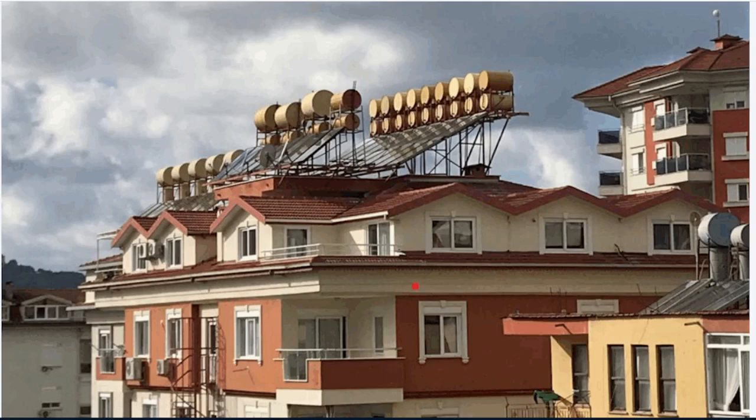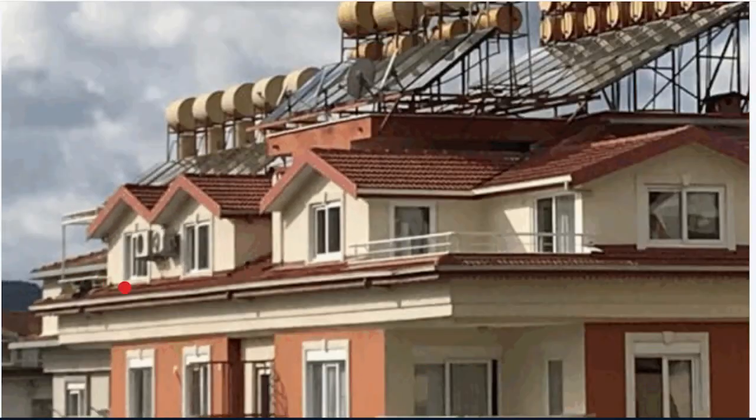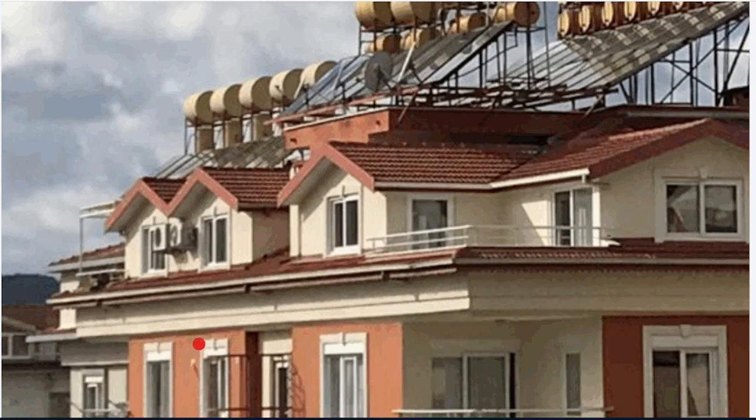Again, look here. We can easily understand completely. He did an 80 centimeter console, even maybe less, 80 centimeter up, and from here they did a slope. And this slope, according to the rule, should not be less than 30 centimeter.